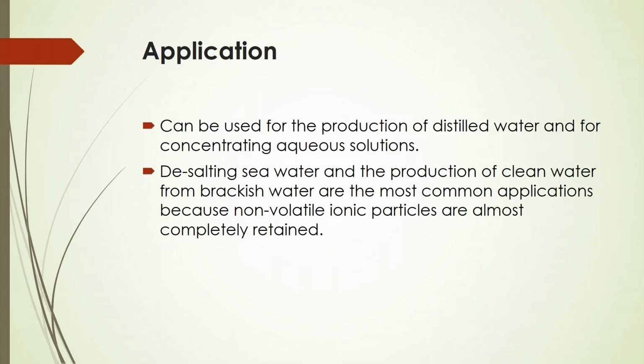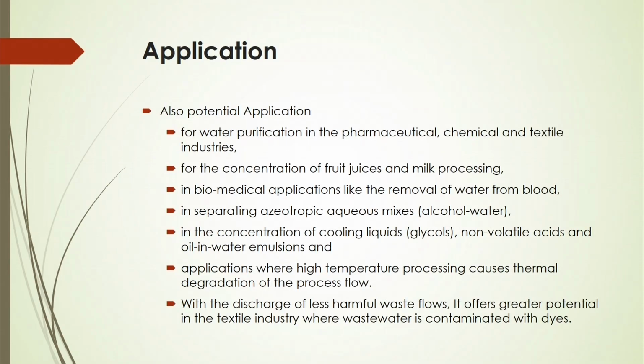And you can use this membrane distillation process for the production of distilled water and for concentrating aqueous solutions, and also desalting seawater, and the production of clean water from brackish water are also important applications, because non-volatile ionic particles are almost completely retained by membrane distillation.